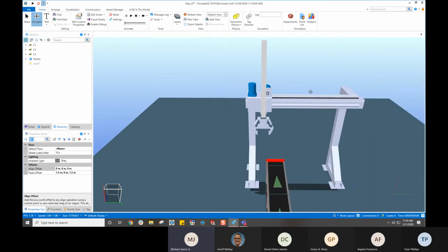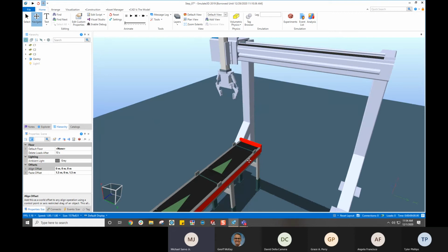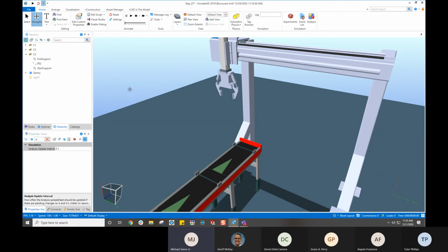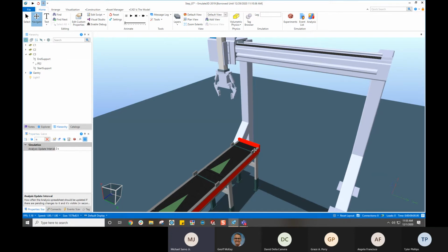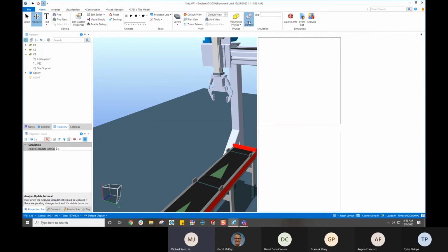And so we know that we've got those properties we've defined on the gantry. We explained that. The photo eye down here on this conveyor has a property called is blocked and one called is cleared, and those are contacts. Is blocked is like a normally open contact, and is cleared is a normally closed contact. I'm going to wire that up to my PLC to tell my gantry when there's a part present to go pick. So let's wire it up.